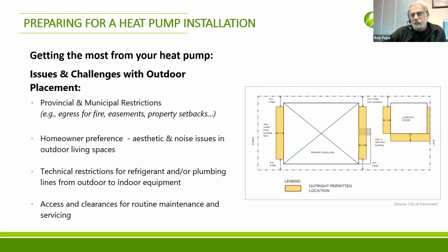So there is... The problem is that the oil will separate out of the refrigerant, right? So you can get a device to prevent that from happening, to mitigate that. For example, Carrier has one, Trane has one, York has one in their installation manuals.